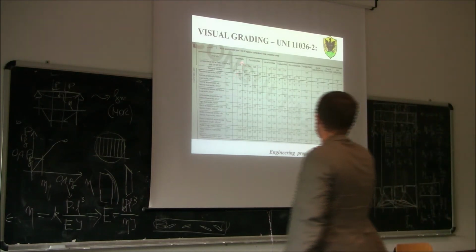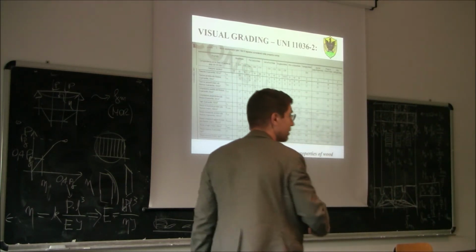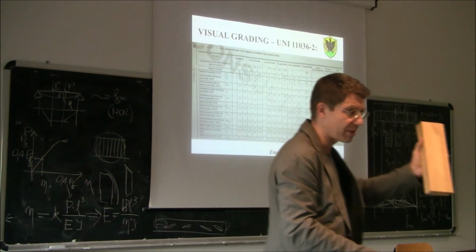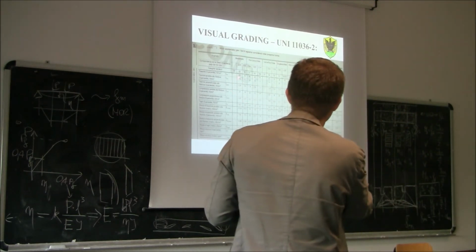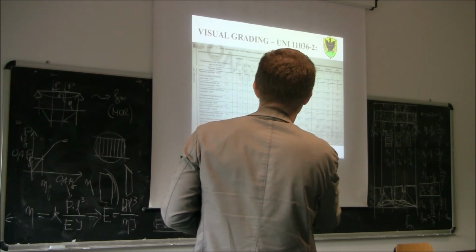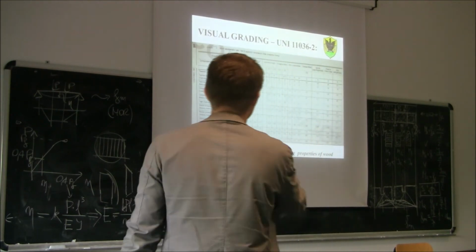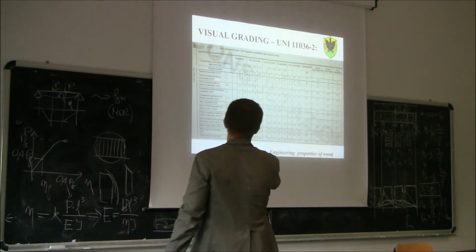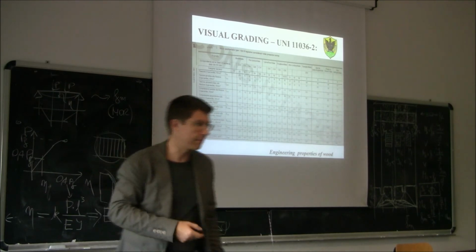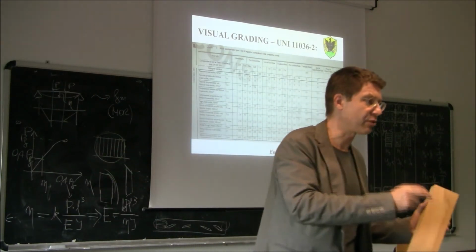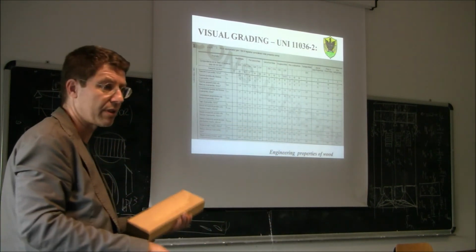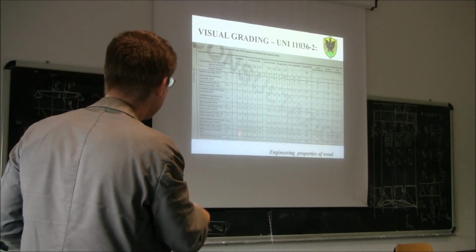And here you can see the properties, the properties used in the usual design. So if you are classified as S1, since S1 does not have a number, you need to take the closest one, which is S2. So you get 25 of characteristic bending strength, 15 tensile strength parallel to the grain, and so on. So you have all the quantities you need there. So basically S1, S2, and S3 are associated with a strength profile, with the set of properties that we will then use in design.